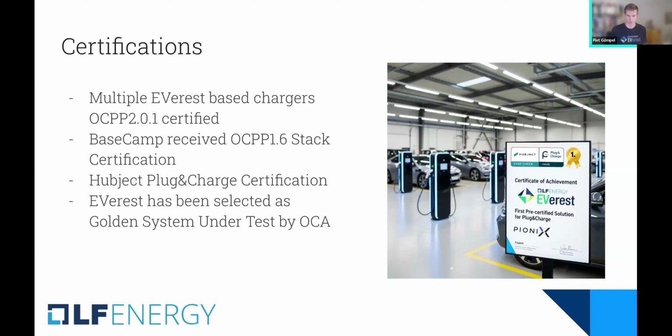We cannot call it the EVerest stack certification, but technically, if you use EVerest, you can be really sure to use an OCPP 1.6 compliant stack for all feature profiles that are available in OCPP, so including security white paper and smart charging and additional blocks. The EVerest stack has been Plug and Charge certified, so that's really the EVerest stack by Hubject by passing the EVSE check.